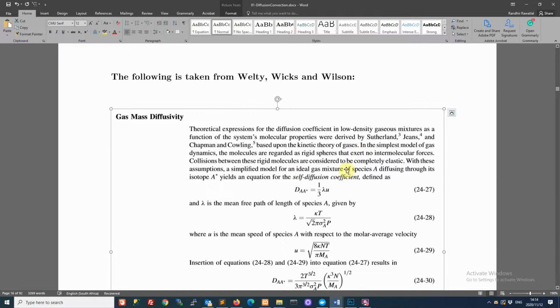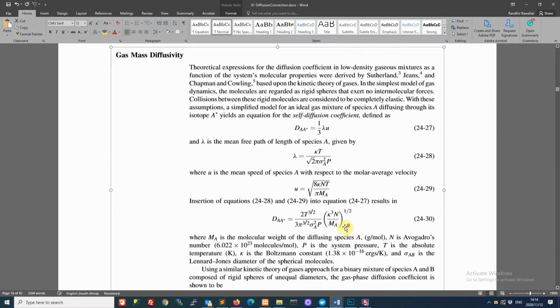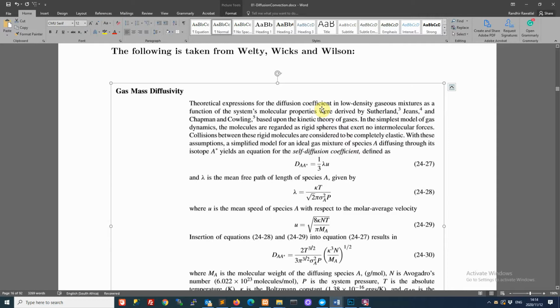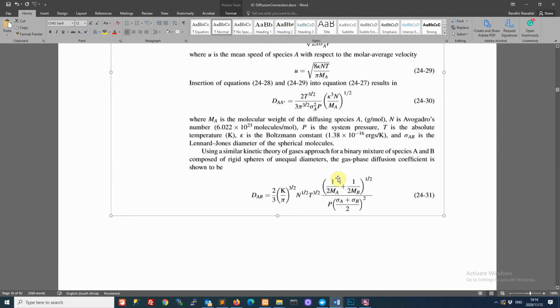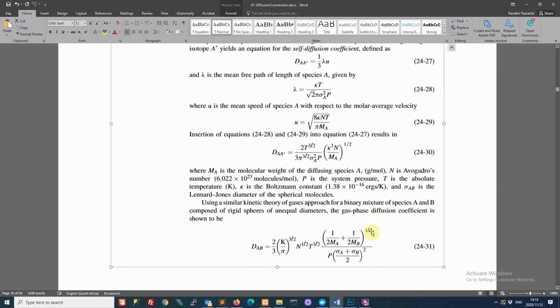So if we know it's a gas phase system and it has a relatively low density, and those are typically precisely defined, so we set some criterion like the density is less than 1 kilogram per cubic meter and things like that, then we know that this correlation applies. So it's a matter, if you like, of following the sequence simply: identifying the type of mixture that we have, then looking up the appropriate correlation for that, and then assembling for ourselves the various properties of the chemicals involved, and also knowing the operating parameters of the system. And then we just use the correlation and estimate the diffusivity.